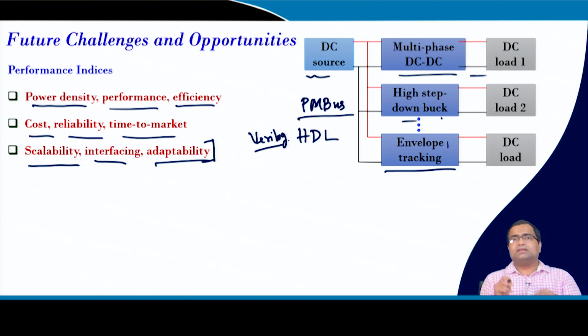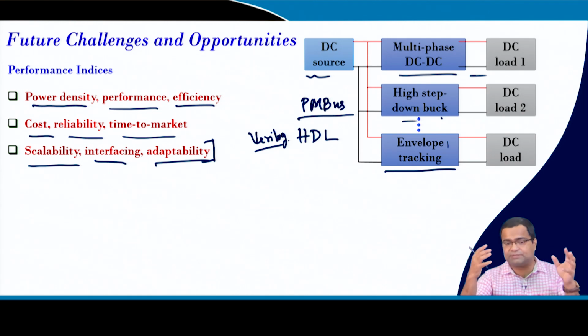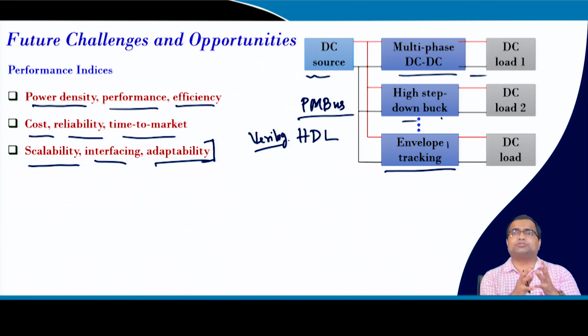So, these HDL languages are basically platform independent. So, you can use this HDL language and develop your controller, you can prototype using FPGA, and when these are tested fine, this can be synthesized by any professional circuit simulator tool or software like Cadence, Synopsys, and then you can synthesize the particular digital circuit using the process technology that you are going to use. Okay. So, it should be an adaptive solution.